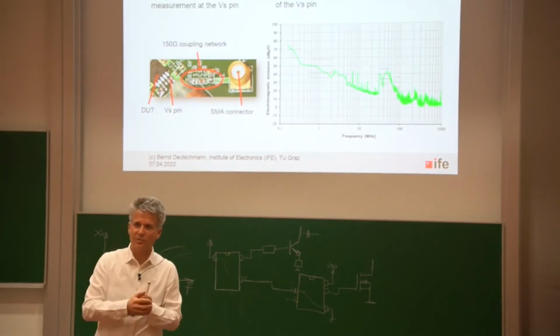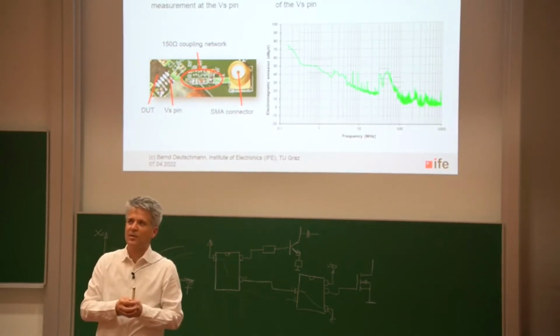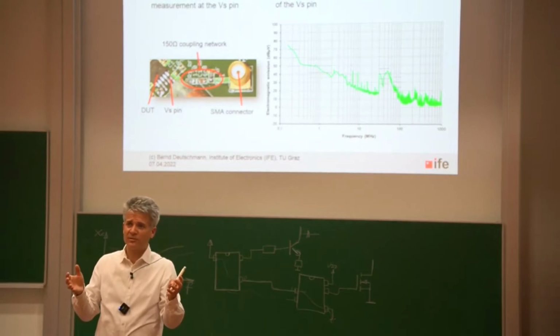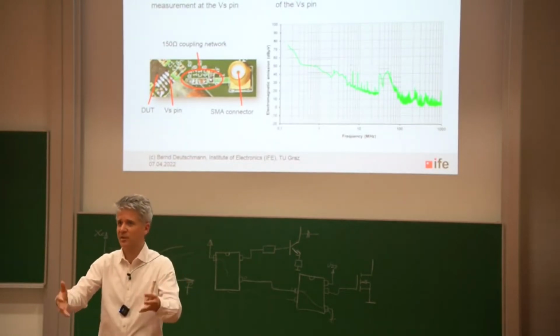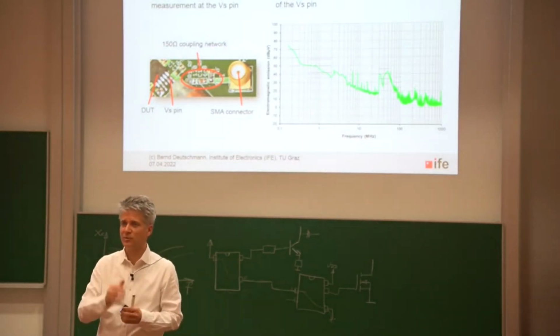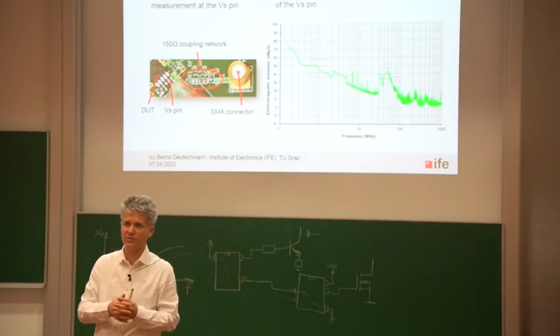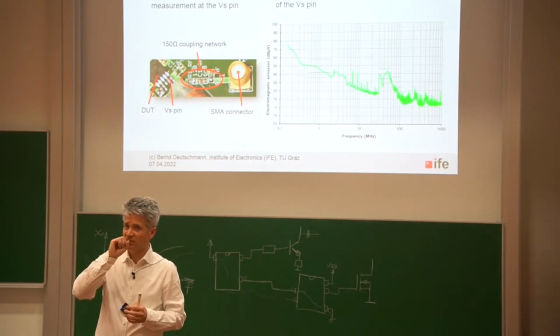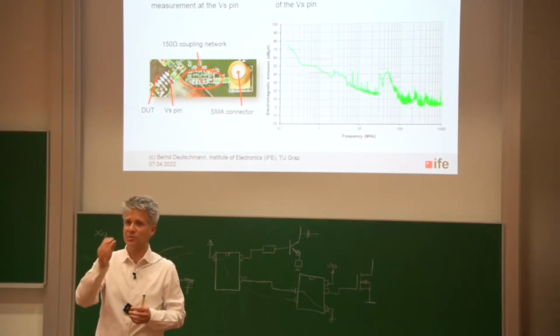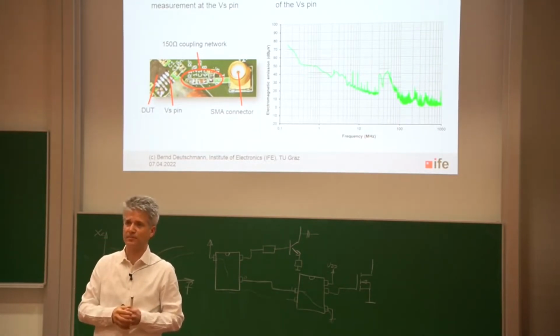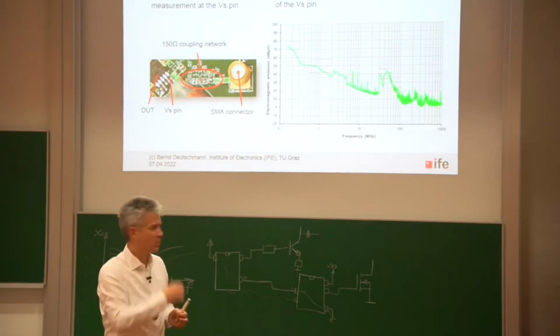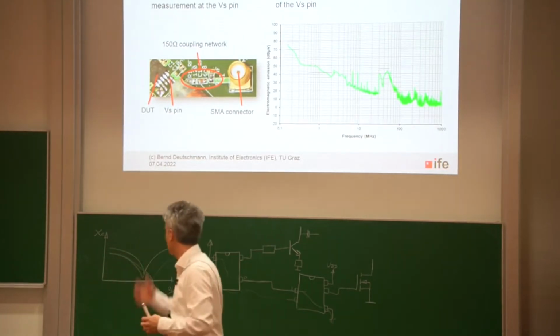So I can define in which frequency range this thing. But it has to do something with that because I'm changing something. I'm really changing some settings at the EMI receiver at this frequency range or at this frequency position. But actually what I'm changing is the input bandwidth, exactly the resolution bandwidth of the input filter. And this is the reason why we have a jump here. So let's focus on that.